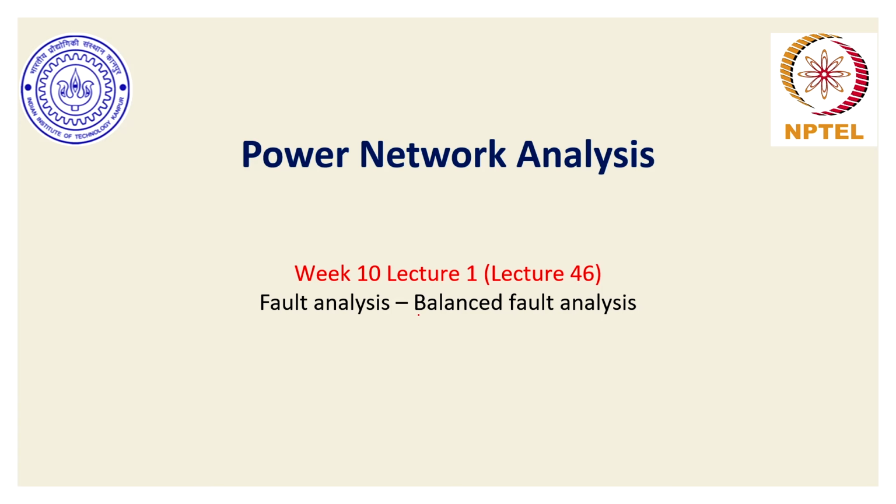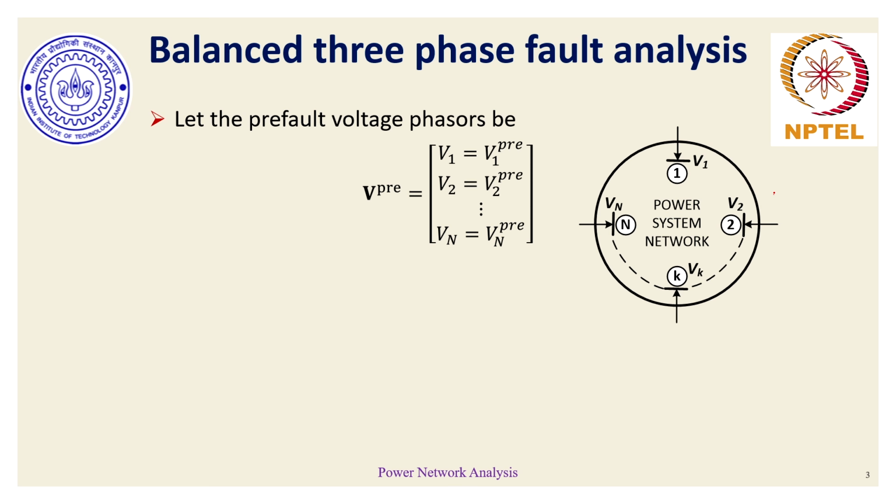In today's discussion, we will take up the application of Thevenin's theorem to understand in detail how balanced faults, three-phase faults, can be analyzed in a very unique, beautiful, simpler fashion. So what we have here is a usual n-bus network. We have also seen this sort of network while discussing power flow analysis. In fact, I have taken the same diagram from the power flow analysis module.